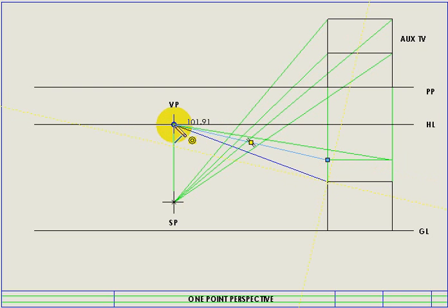And what I'm going to do is I'm actually going to find the roof first, because I find if I start with the bottom portion, I get confused with all the lines, and then you as the viewer will also struggle to see what I'm trying to do. Now I've tried to put this point down to my stationary point, and where it connects with the actual picture plane, I'm going to go ahead and plot my points on each one of these lines. Makes it easier for me to project straight down from each one of these points.